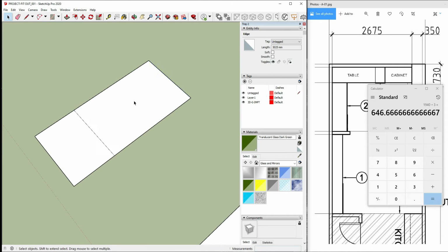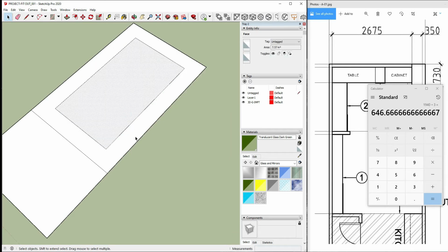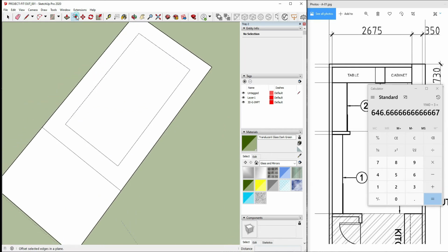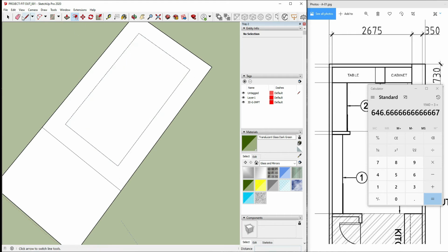After collecting some of the lighting fixtures from the 3D Warehouse, we will now lay out the false ceiling. As you observe, I used the offset tool to create a line for our cove light ceiling and laid out circles of the same diameter as the selected pen light. I also used the push-pull tool to create a realistic model for the drop ceiling.